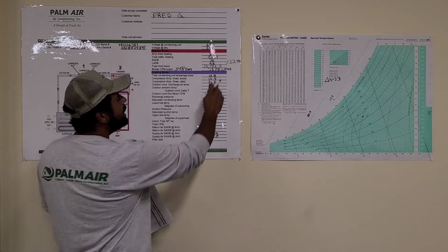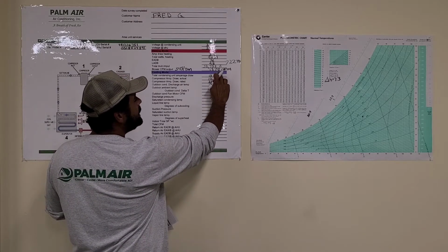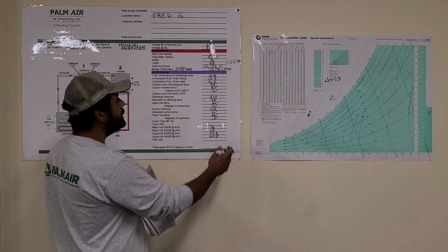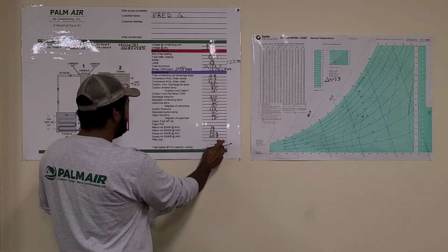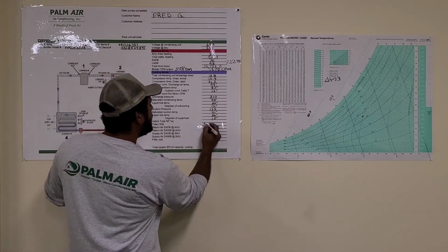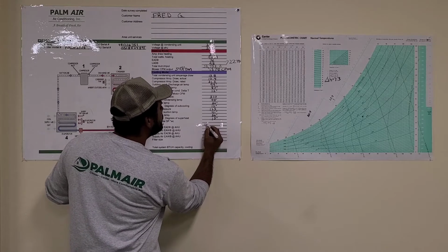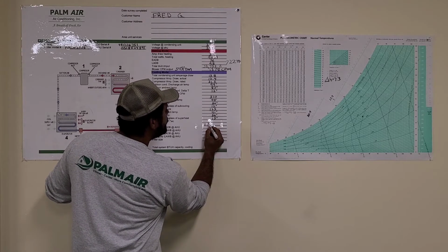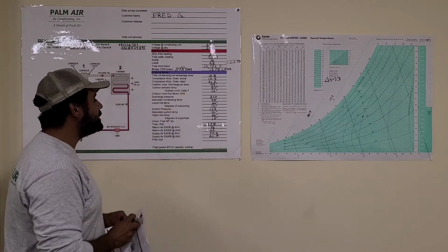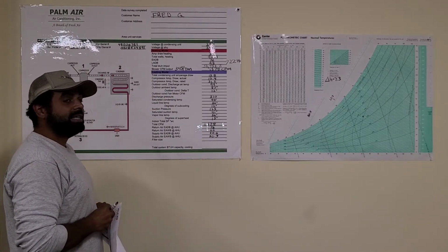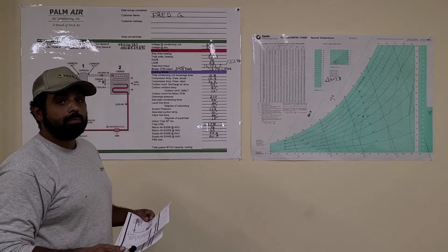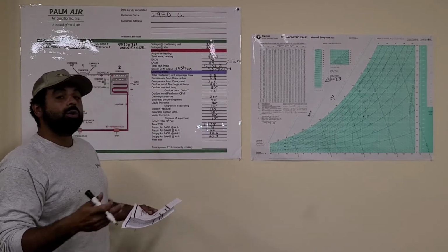This number, 1378, we're going to use in our next equation. We're going to move this number down here into total CFM. Again, that's just the number. We're just moving it down. 1378. The next thing we're going to do with this diagnostic is find out, is this removing the right amount of BTUs in the cooling mode?